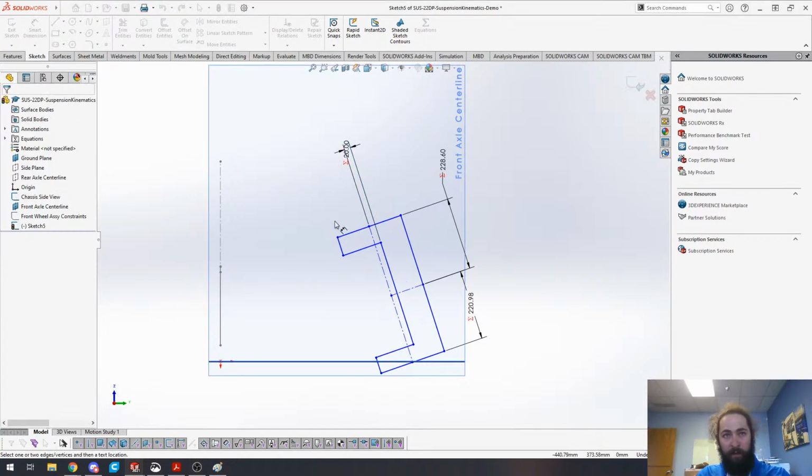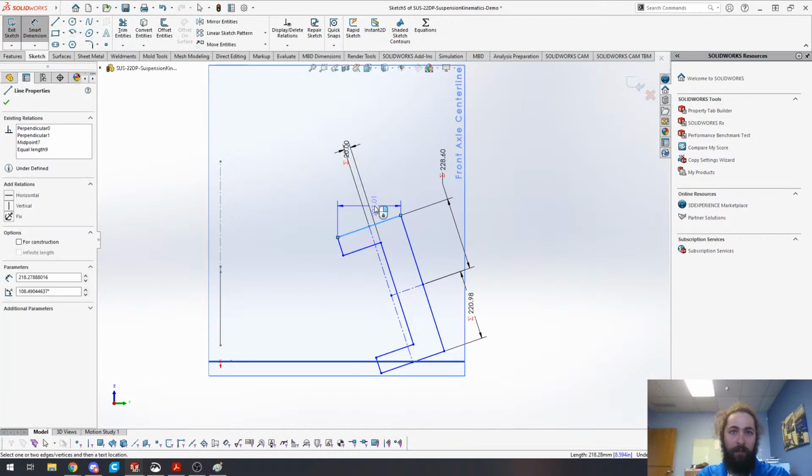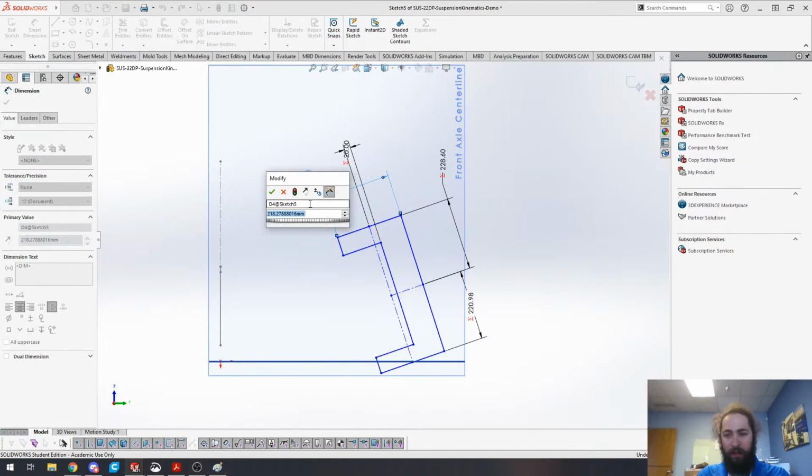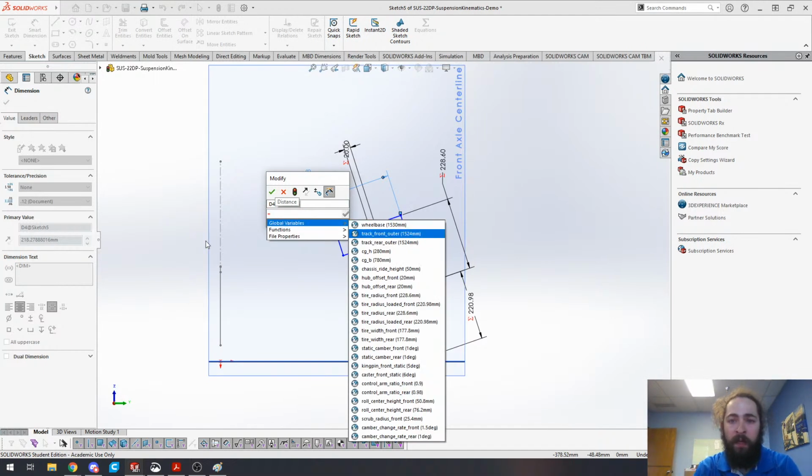And this can be different in the front and the rear as well, based on how you set up how you have your wheel shells. If you have wider tires in the rear or wider wheels, different back spacing, different upright geometry, there's a lot of different reasons why that could be differently sized. So in this case, again, we have hub offset front and rear. We know those are going to be the same value because we're running the same wheels and same uprights front and rear. But again, this could change.